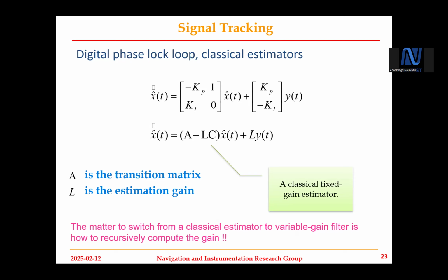Traditionally, that was because in many cases, especially in downtown or urban environments, we also have a reflected signal, and we don't always kill that multipath signal. Sometimes that could be constructive multipath. That means we may dedicate two channels to the same satellite signal, and then we judge and combine them, or we pick the better one, deciding this is the actual and that is the delayed.